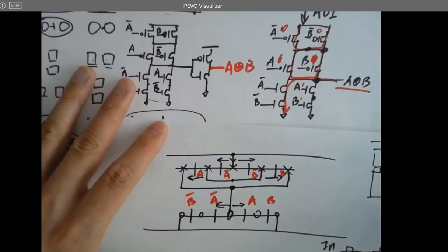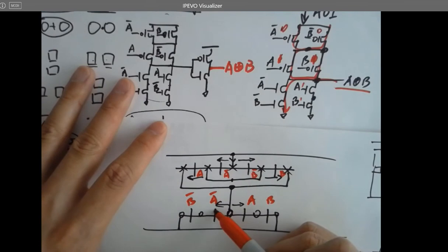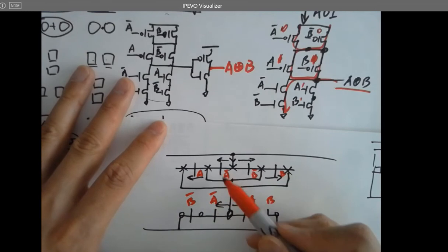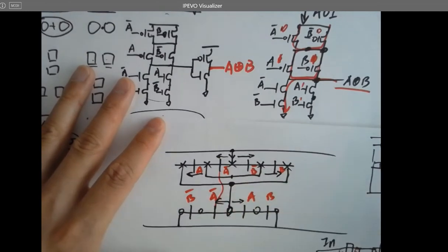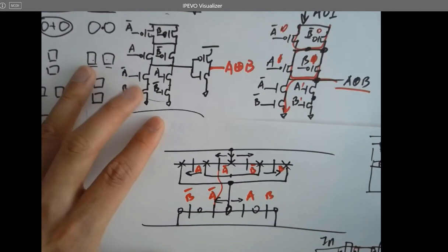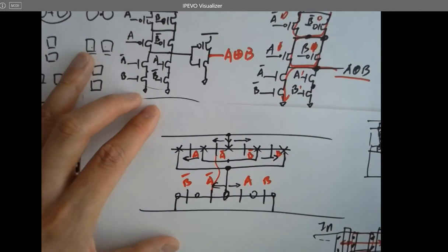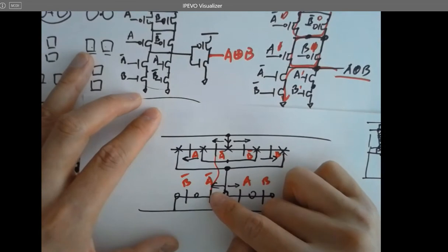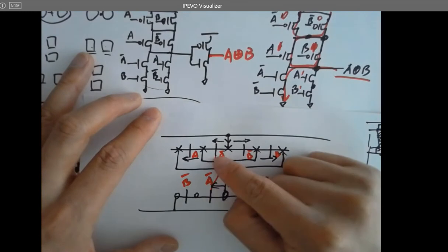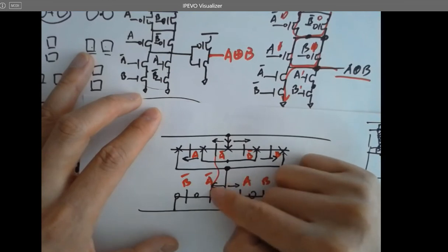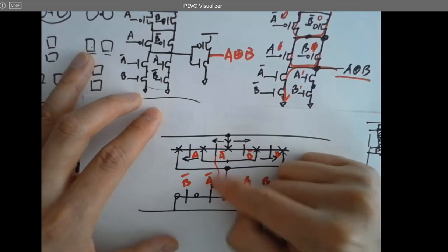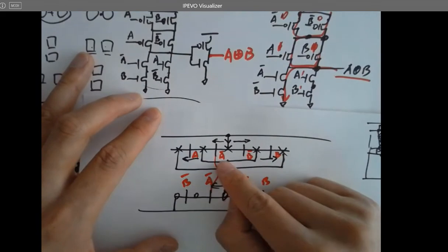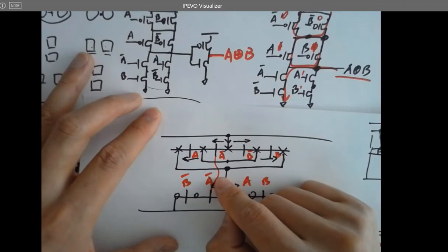Just want to make connections. A0 should be shorted to A0. So imagine you are laying out this circuit in Electric VLSI. Can you make this connection directly using the polysilicon layer? Are you shorting any circuits? If you directly draw polysilicon and the pink color thing and short these two signals together, are you going to short any circuits? No, because these are metal ones. This is poly. They are in different layers.